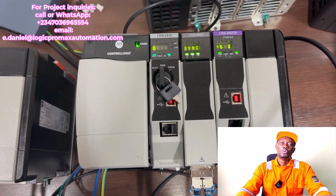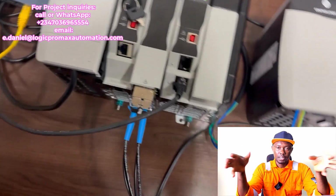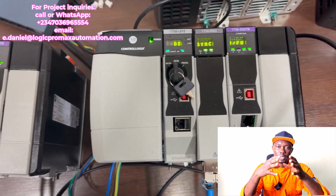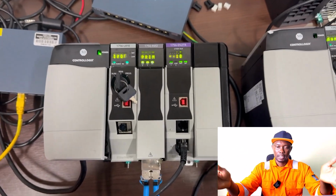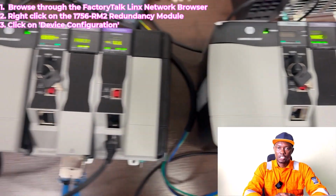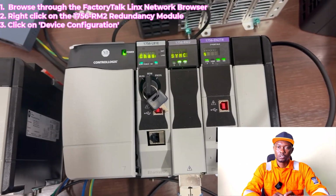In this video, we go through the configuration of the redundancy modules themselves. Then we will do the PLC code download. Then we will do the synchronization of the redundancy controllers, the partners. For you to configure the redundancy module, you have to browse the FactoryTalk Linx network browser, identify the device, right-click on it and select device configuration.